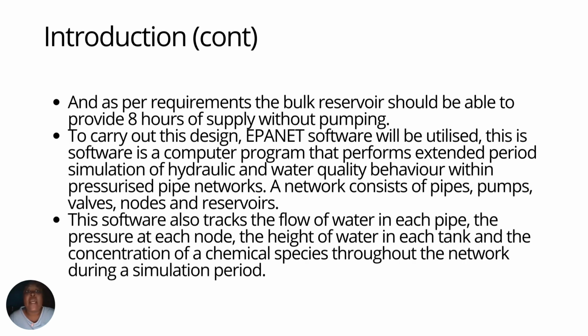Now, as per requirements, the bulk reservoir should be able to provide 8 hours of supply without pumping. To carry out this design, the EPANET software will be utilized. This software is a computer program that performs extended period simulations of hydraulic and water quality behavior within pressurized pipe networks.